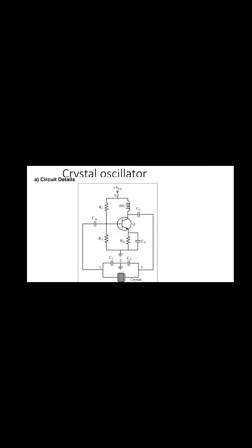So in order to use the crystal, it exhibits the piezoelectric effect. If AC voltage is applied across the plate, the crystal will start vibrating at the frequency of the applied voltage and produce AC voltage. In order to use the crystal in an electronic circuit, it is placed between two metal plates. The arrangement then forms a capacitor with the crystal as the dielectric.